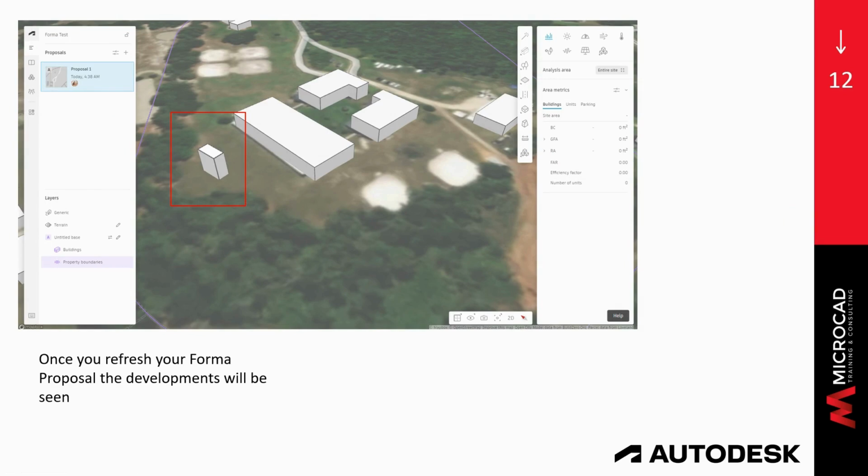But what is going to happen if I make major changes or updates to the proposal? In that case, what is recommended is to create a new proposal, right? So you can create a new proposal. That way, when you send it to Revit, you're going to be able to as well add or create your new building and continue with your analysis, right? So remember, from Revit to Forma, as many updates as you want. But if you're having major inputs on your site, on your masses and all that, what is recommended is to